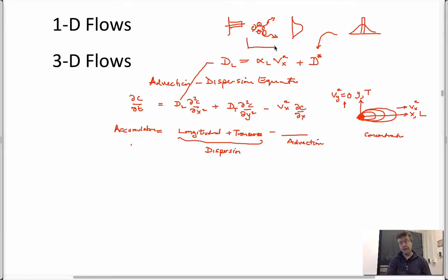If you look at it along the length of the flow, this would be y. Maybe we should use y for that. Then this would look something like this. You start off with a drop of ink, and it gets mixed as it goes downstream. It's physically carried downstream by the advective velocity of the water, and because the particles diverge as they move downstream, for the 3 mechanisms that we talked about last time, it spreads out in this Gaussian distribution.